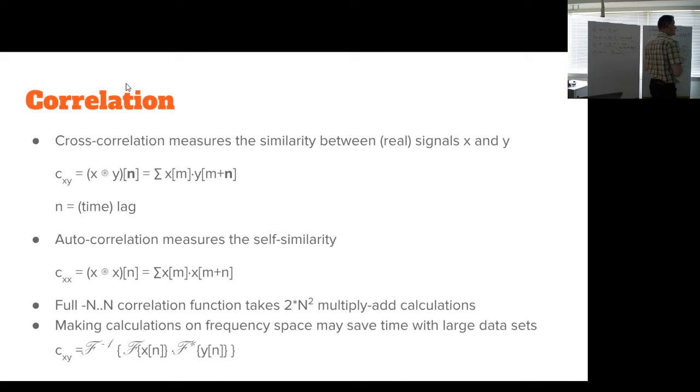An application of that: trying to find a leak in a pipe, such as a gas pipeline, you can use the acoustic correlation technique. If you have a pipeline and somewhere a leak, it is a random noise source. Then you set a couple of microphones, one here, another there. You have the sound waves from the same source coming to these two points at different times.